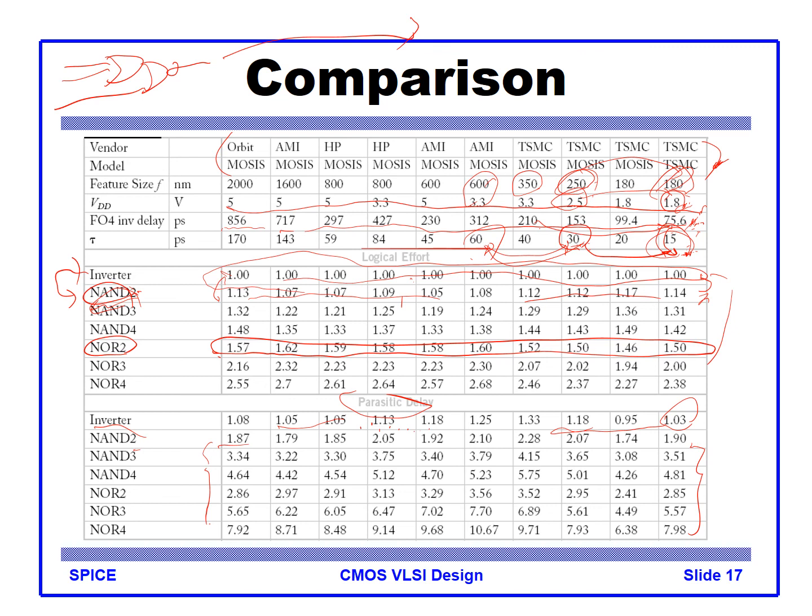You can change the OR gate to an AND gate by inverting the input and output, changing the polarity of the input and output. That becomes the equivalent circuit. Bubble pushing.